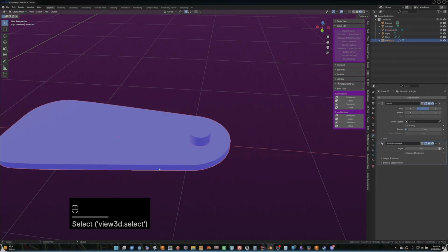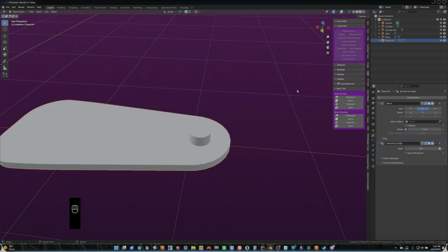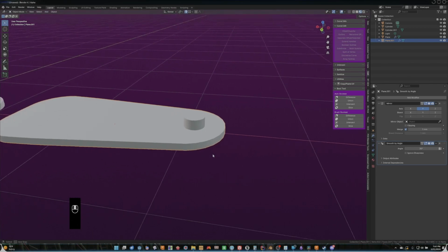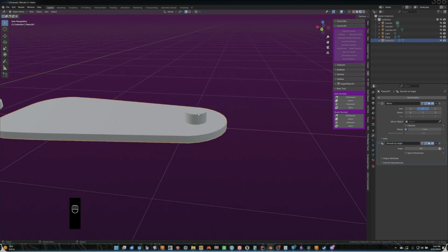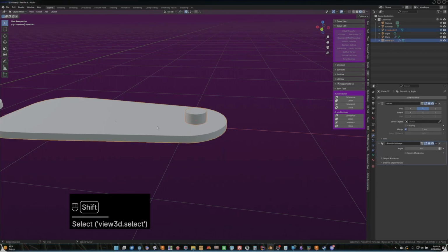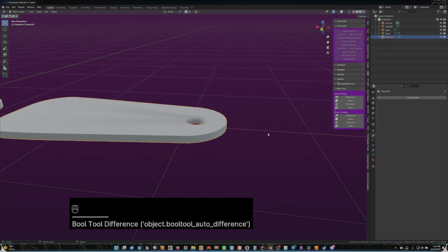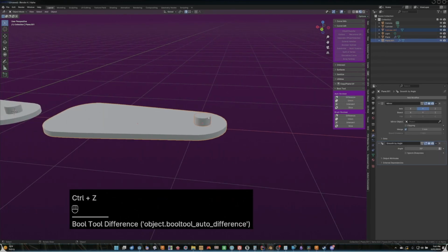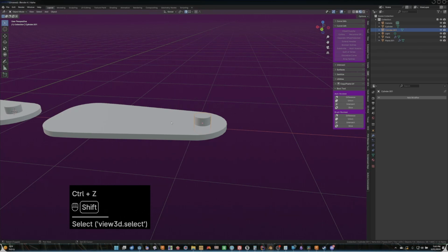So if you select the body that you want to cut, you know what, I can turn off face orientation mode because I think we're done explaining that. So now we can take our body that we want to cut and the tool that we want to cut with. I believe we select the tool first, then the body. Difference? Yes. So select the tool that you want to cut with, then the body.